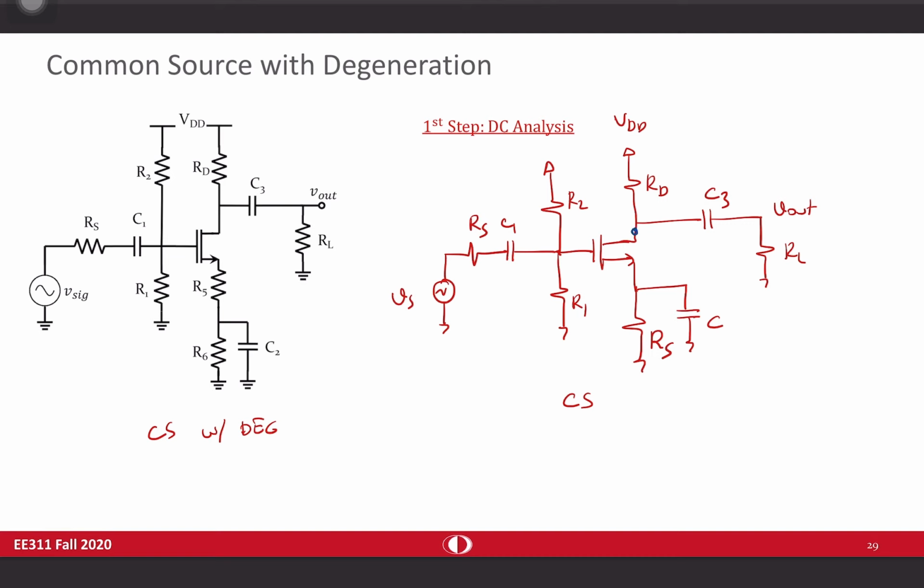This circuit is still a common source amplifier. Why? Because take a look at the nodes, drain, gate, and source. Source is AC-wise grounded still. Nothing changed. The only difference is, instead of the ideal current source in here, instead of pushing a well-defined current from the drain or source of the transistor, you put a resistor, and this resistor is for resistor biasing. Eventually there will be some DC current passing through here, and the value is set by this RS, RD, R1 and R2.